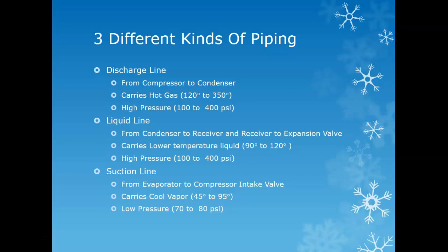So the best way, if you have something like that, take a little soapy water if you suspect there's a leak and it can show up where the leak is. Don't be tempted to put your fingers over it. And that goes for all pneumatics. Considering that you can pressurize pneumatics into the thousands of psi, not a good idea.